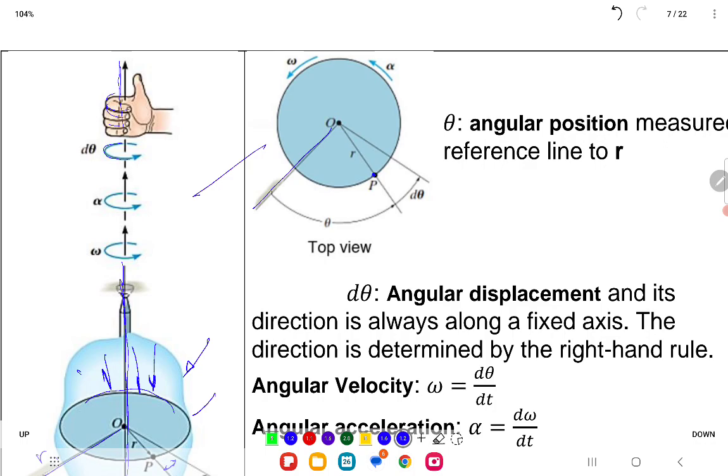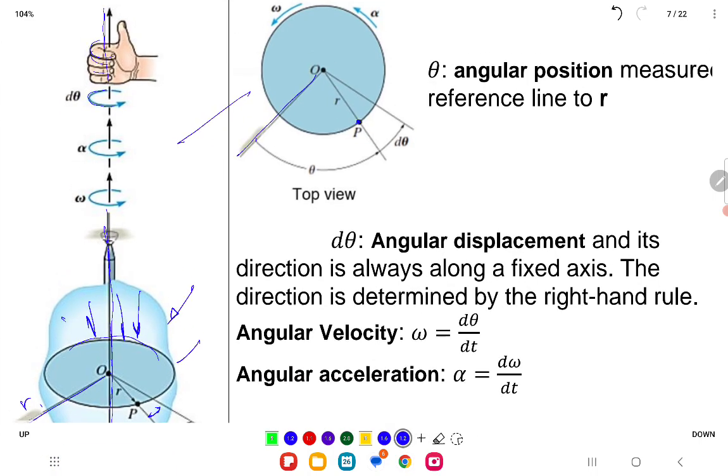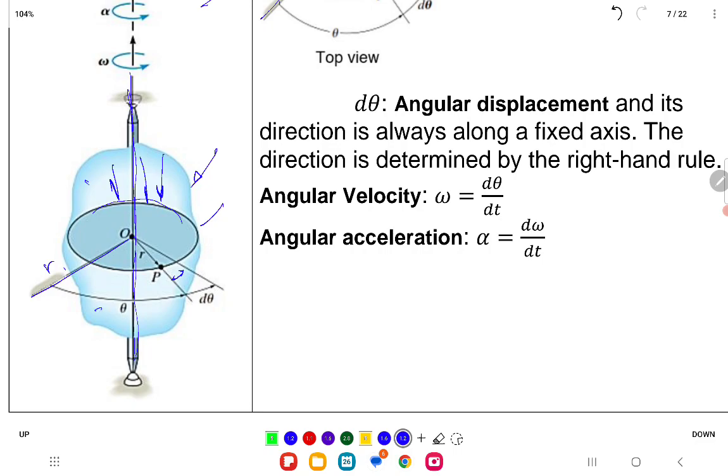If you know the angle and you can measure the time, what I mean by this, let's say that you move to 30 degrees, and then just to increase it a little bit, let's say delta theta is like 2 degrees, and then count the time. Let's say, if you have really precise time, 0.2, then you divide the increment of the angle by the increment of time, you can get the angular velocity. So the angular velocity here is equal to the rate of change of the angular displacement with respect to time. That's called the angular velocity.